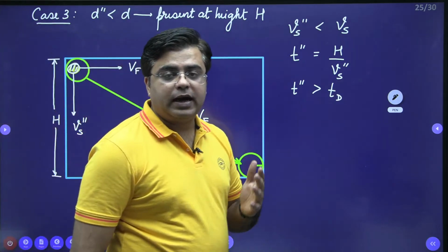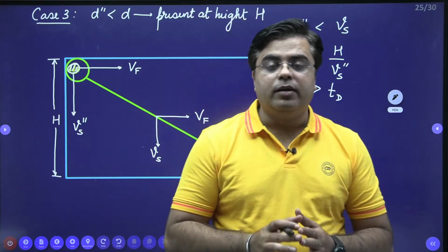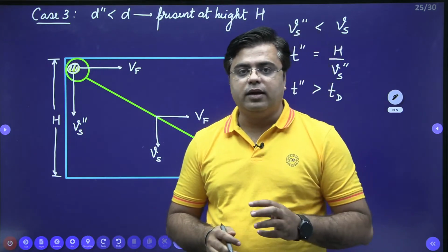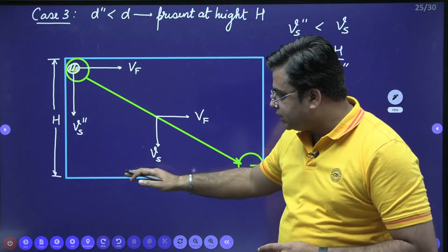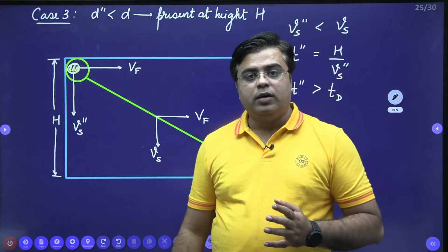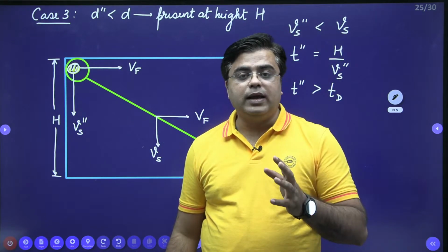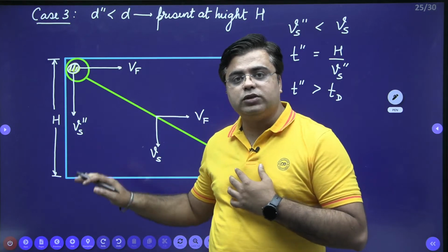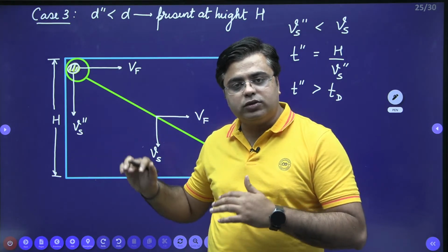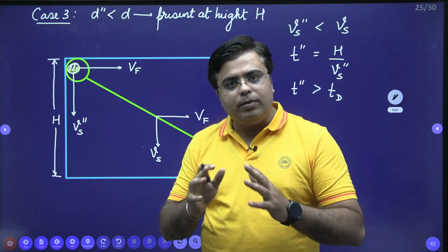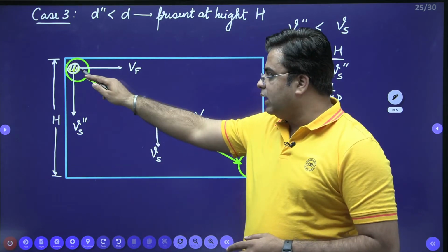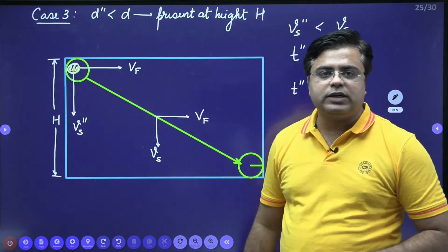It means that the time required by the smaller particle to reach the bottom of the settling zone is more. But we are not providing that much time for the water or the solids to settle. So in the available time Td, these solids will not reach the bottom of the settling zone.